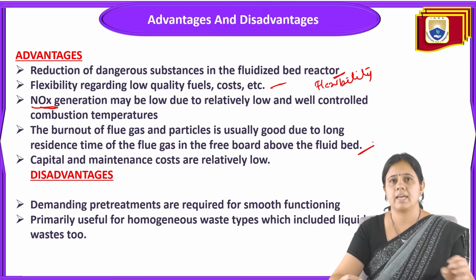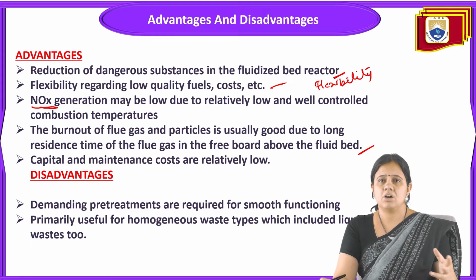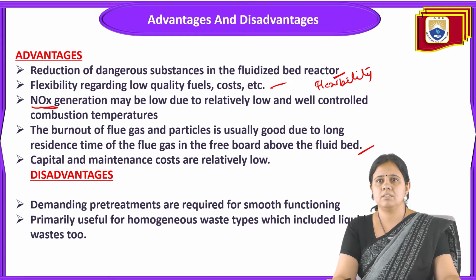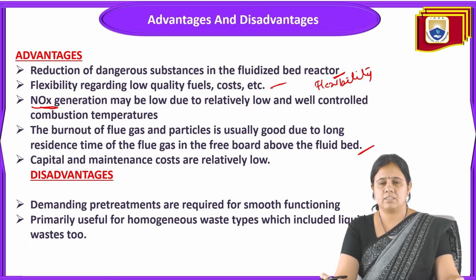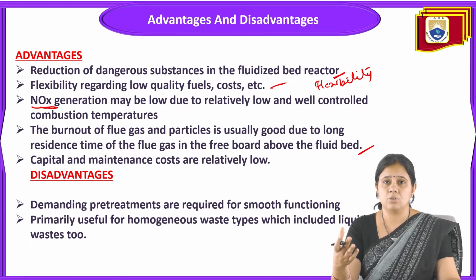So this is again a very good advantage. The benefit is that the burnout of flue gas and particles is usually good due to the long residence time of the flue gas in the freeboard above the fluid bed.